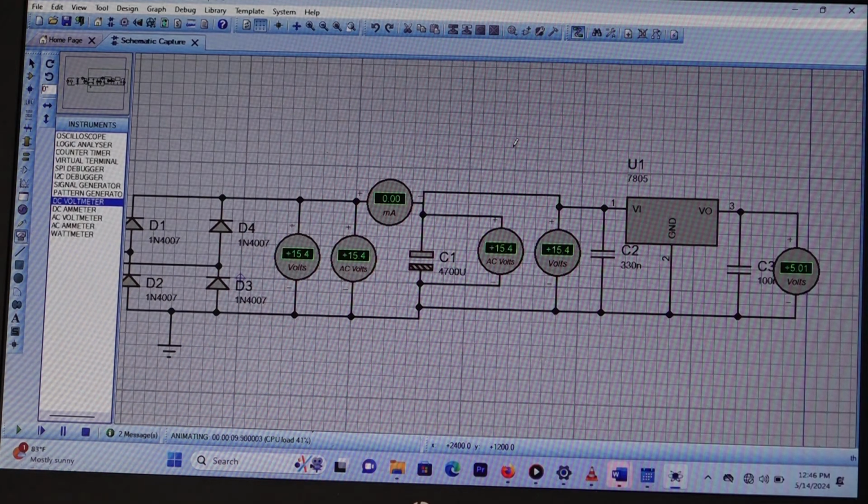So the input voltage of the voltage regulator is 15.4 volt. You see that even the voltage across the filter unit has been decreasing in some decimal points. Previously it was what? 15.8. Now it's 15.4. I don't know if you have noticed. Those are the challenges that we encounter in the simulation part. Are we together? What is the output voltage? It's 5.0 volt. We still have the load part, which is the power indication part.